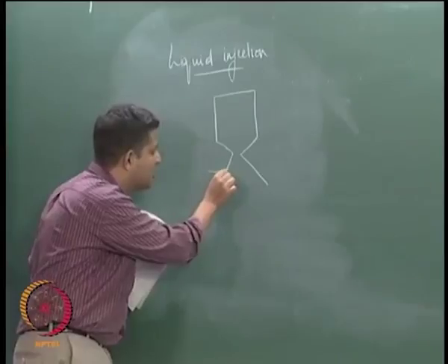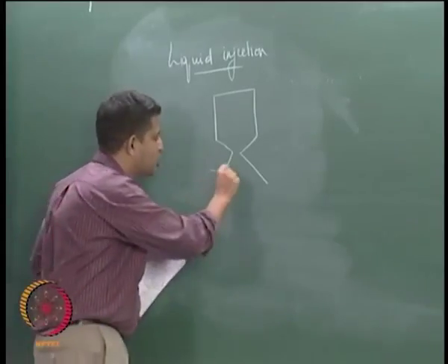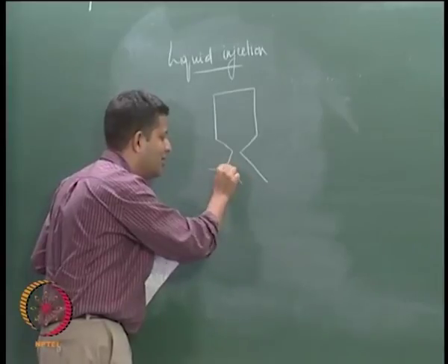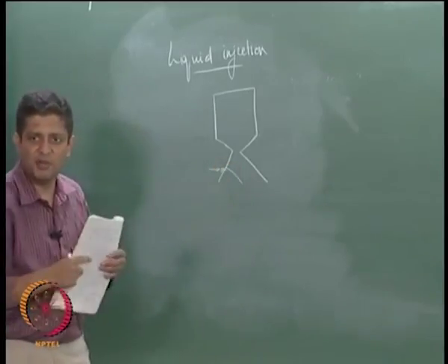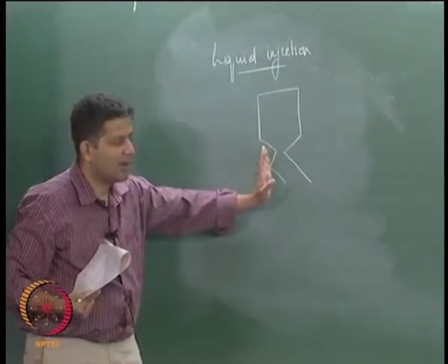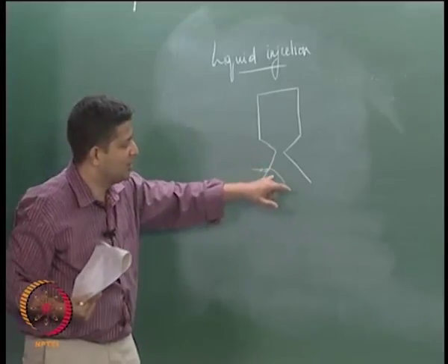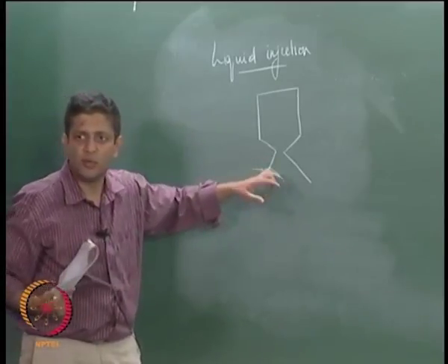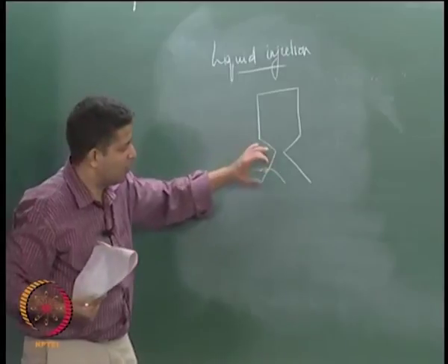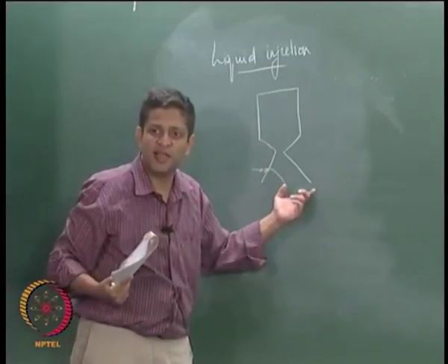Because of the liquid coming out here, an oblique shock develops upstream of this liquid injection point, and because of this you will get a side force, right, because in this portion it actually acts as a nozzle being cut off after some length, and therefore it gets you the required side force.